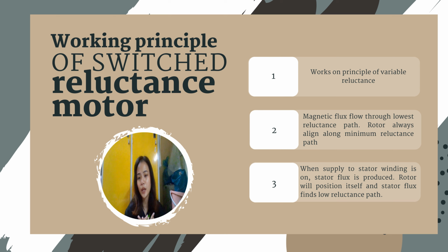And when the supply to the stator winding is on, the stator flux is produced. The rotor will position itself so that the stator flux finds the low reluctance path. And this is the basic principle of operation of this motor.